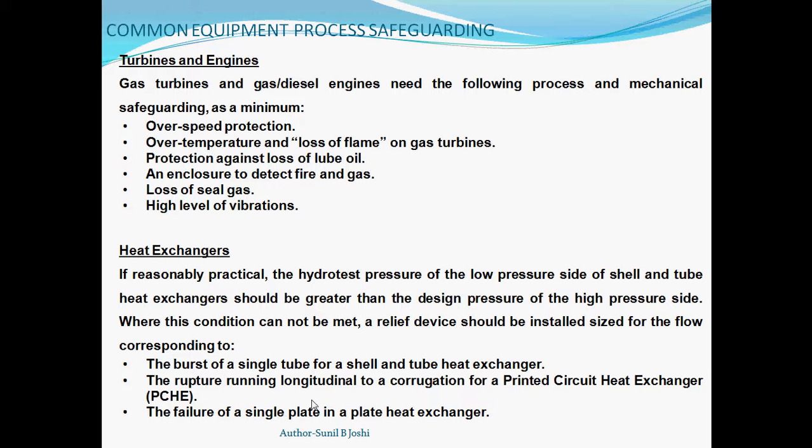So based on what type of heat exchanger it is, accordingly you have to consider the failure of one of the weak components, and then you have to find out the relieving load for the system of the heat exchanger. So you will find the definitive criteria with respect to identification of the scenario from your company specific safeguarding philosophies.